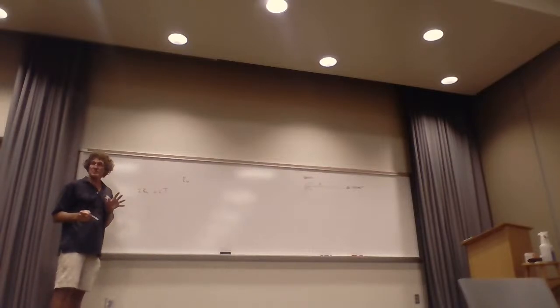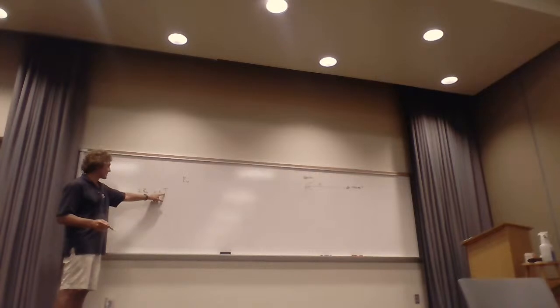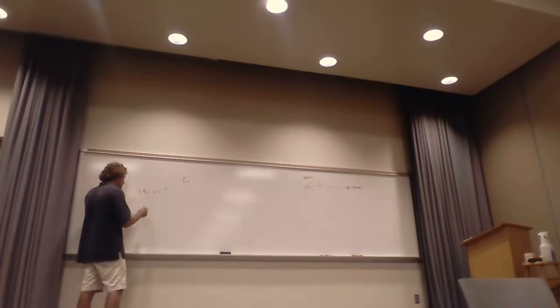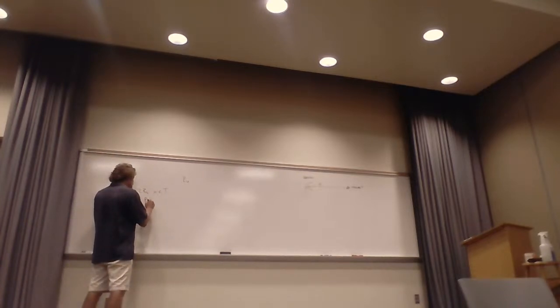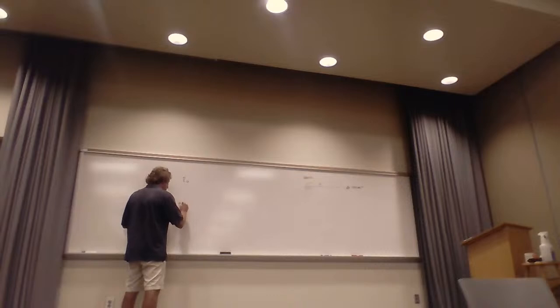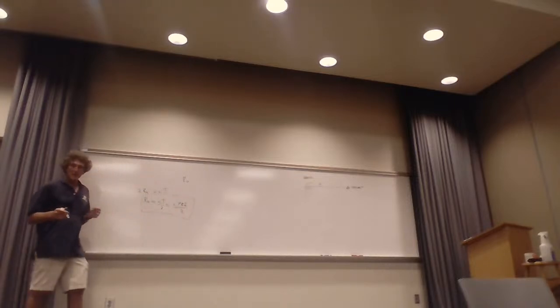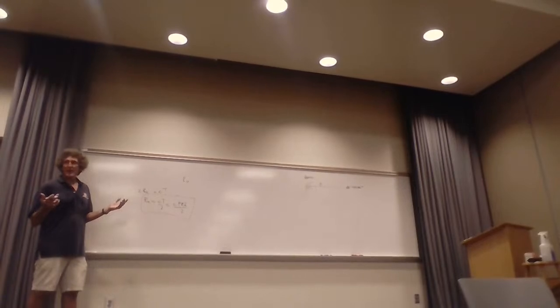If we don't get a pulse back in that length of time, we're about to figure, this is the range, but it's based on this cap T or the PRI. The maximum non-ambiguous range will be CT over 2, or really C times the PRI over 2. So I think your mind should be working right here, and you should be saying to yourself, well, how do you know where it came from?